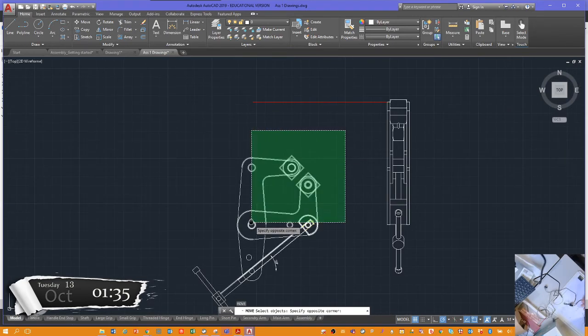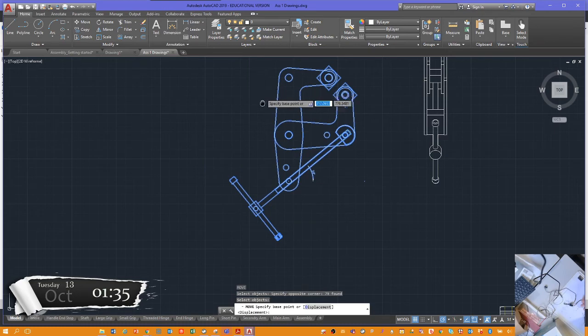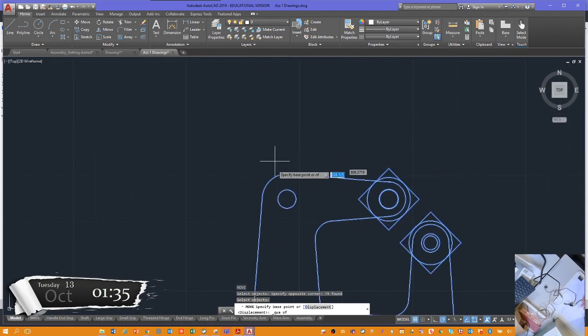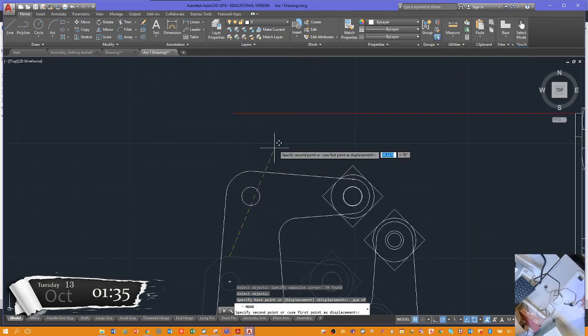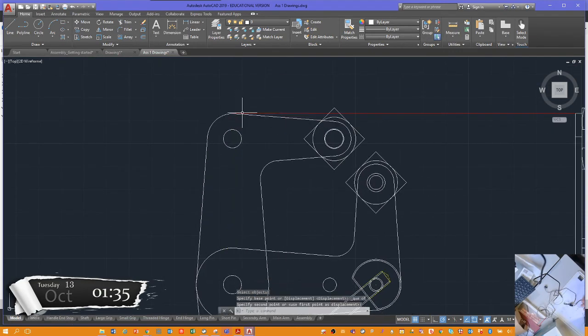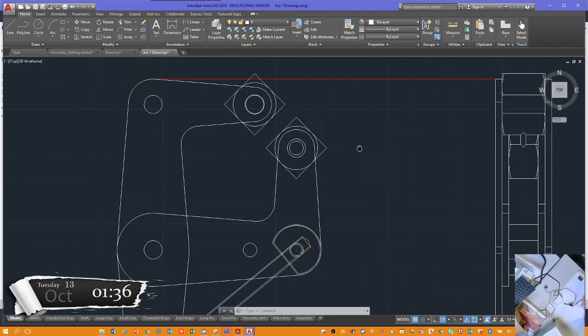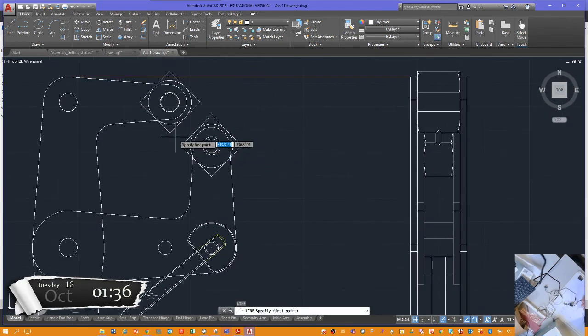So if we just move everything we've done, and we move it, and we go for control and right click, and we use the quadrant, and that's the quadrant just there, and we'll place it, yeah, let's place it at the end point, why not? There. So now everything should line up, he says. If I've done my homework correctly, let's just check, shall we? Look at that. Yeah, bottom of the thing lines up with the bottom of the thing. Crikey. That's our assembly more or less done.